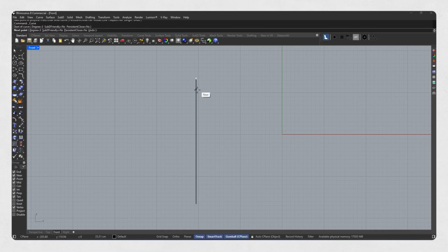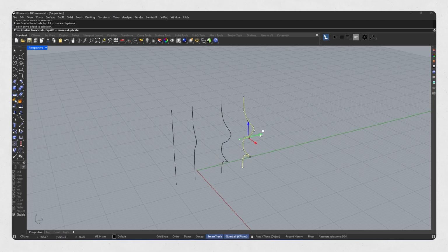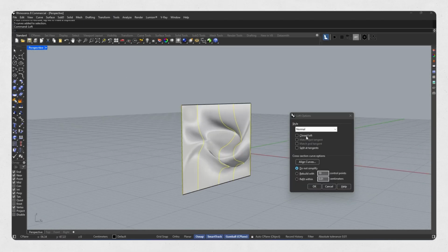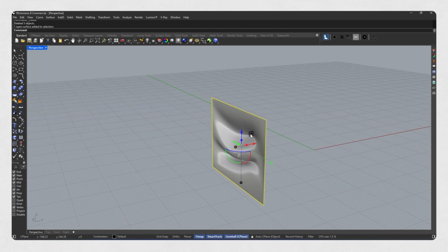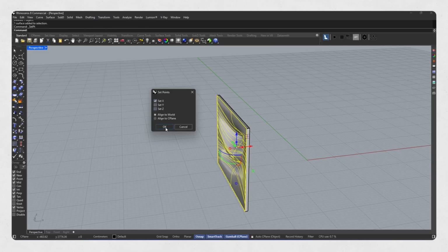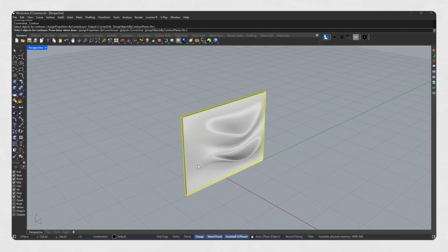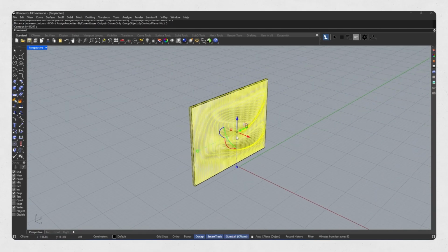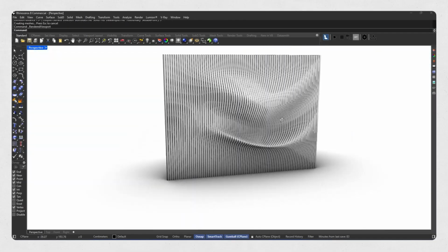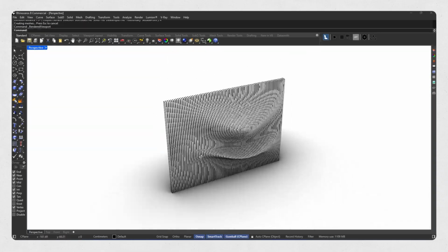Before we dive into the final part, let's do a quick recap of what we've learned in this video. First up, we figured out how to create simple forms using Loft. Then, we moved on to contouring those forms. We added some thickness to the sections and established the main structure. We even modeled a few examples with low to medium complexity. And guess what? We discovered that even those forms that seem super complicated at first can actually be built easily by simplifying our thinking and following these steps.